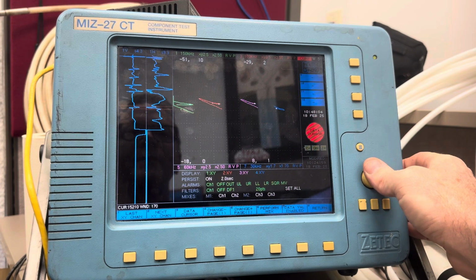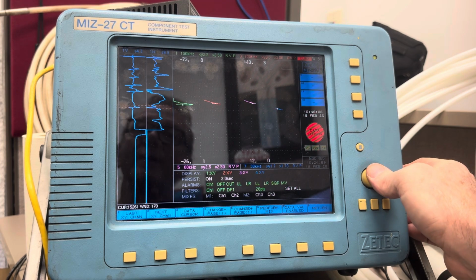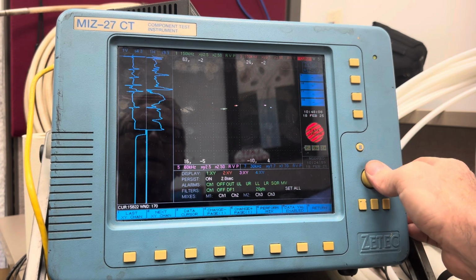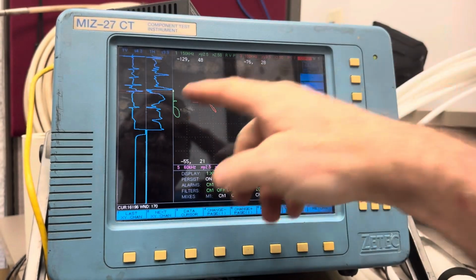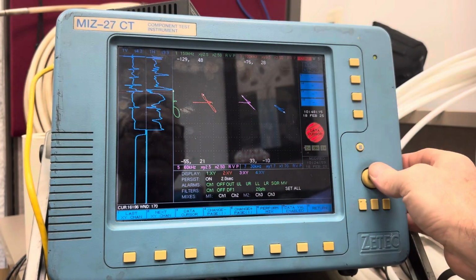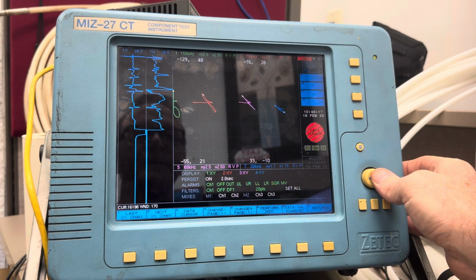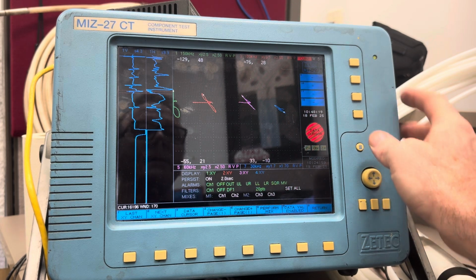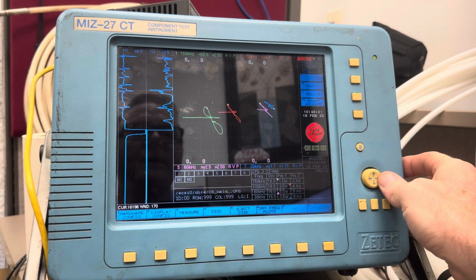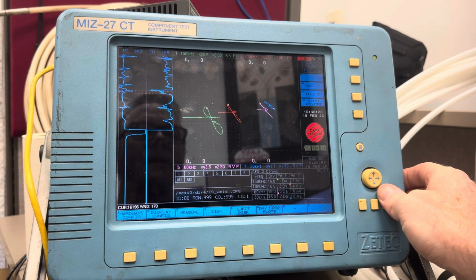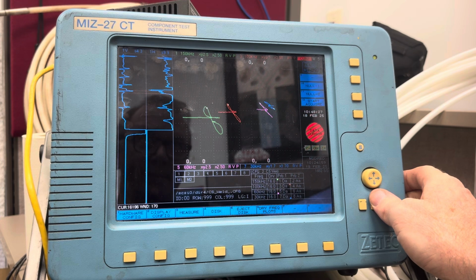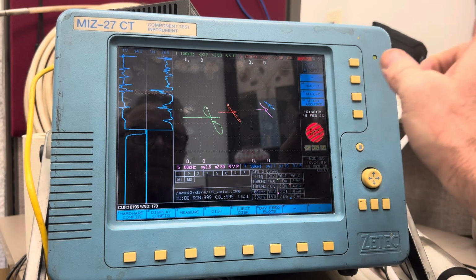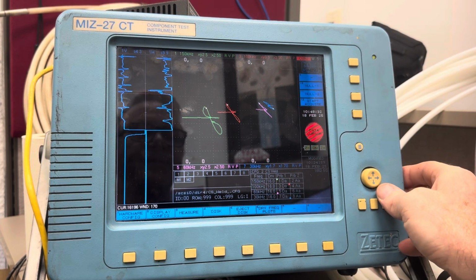So now when we get up to the 80, that's going to be a little farther away from the coil, right, because it's drilled from the OD. Now instead of being at like 30 degrees, it's about 45 degrees or so over here. I have an important point to make here, and that is OD flaws will rotate counterclockwise with decreasing test frequency.